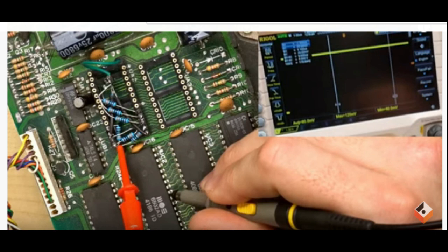This means when the CPU reaches their addresses, they will connect to the data bus and output their register contents. So the NOP generator should not fight too hard with other chips driving the data bus.